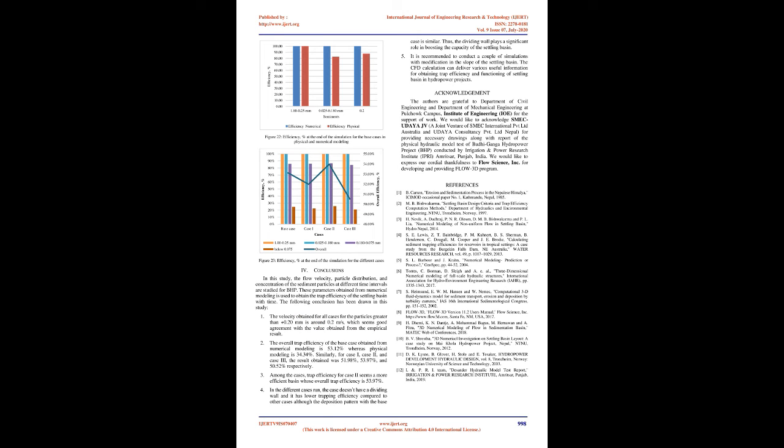In the physical model, the trap efficiency for the range of sediment 1.00 to 0.25 mm, 0.25 to 0.10 mm, 0.10 to 0.075 mm, and below 0.075 mm respectively are 100%, 82.67%, 45.32%, and 23.88%, whereas overall trap efficiency is 34.34% and for plus 0.20 mm is 87.66%. The comparison of trap efficiency between numerical and physical modeling is shown in Figure 22. The trap efficiency comparison between the base case and modified cases obtained from numerical simulation is shown in Figure 23. It shows the overall trap efficiency of modified case 2, i.e. transition angle 8 degrees, is better than the other cases.